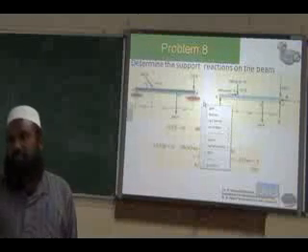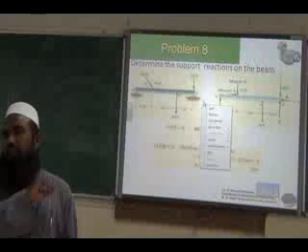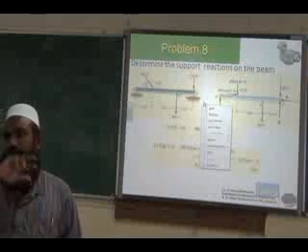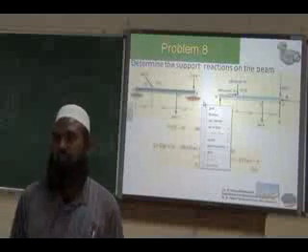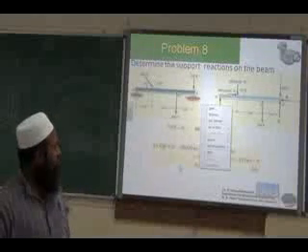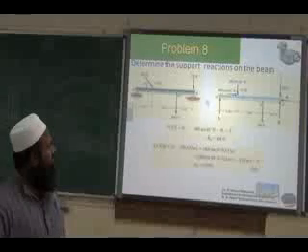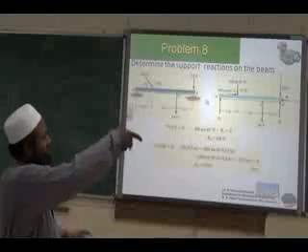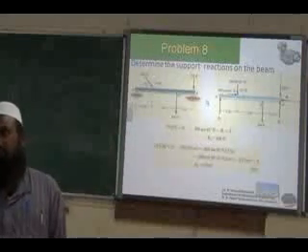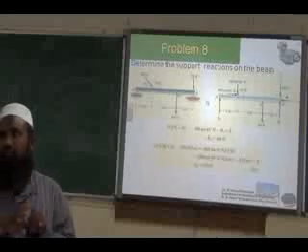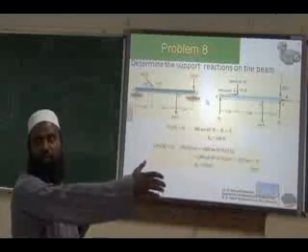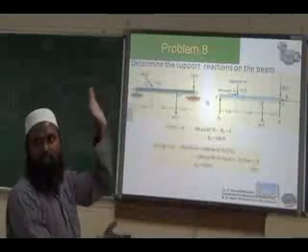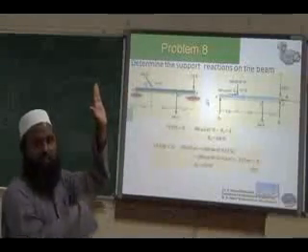And you have to consider the sign convention also. For example, in most of our problems, the anti-clockwise rotation is taken as positive. Okay, clockwise is negative. So if you say Ay from B, what is the direction of rotation? Clockwise. Ay and its moment is taken from point B. So it rotates like this. Ay is acting in this upward direction.